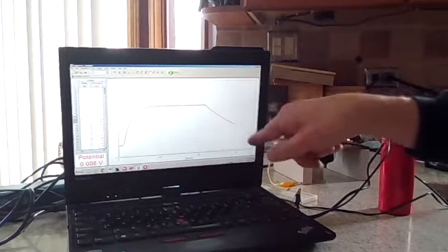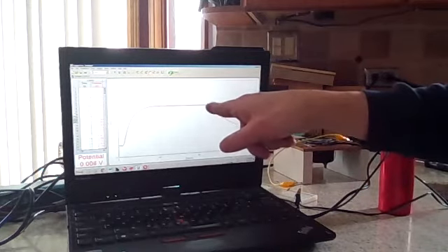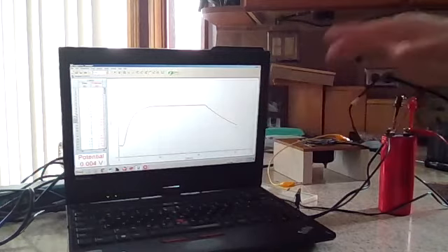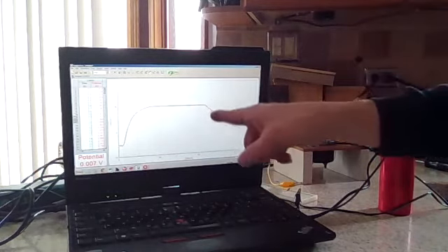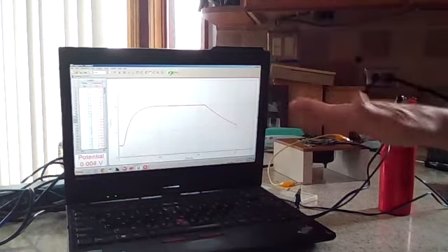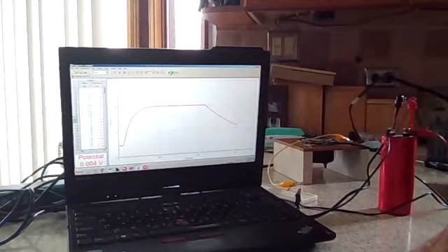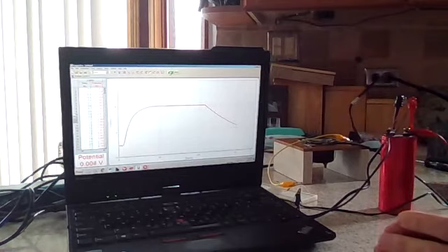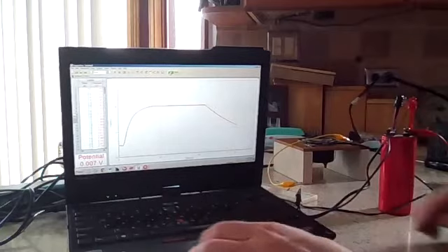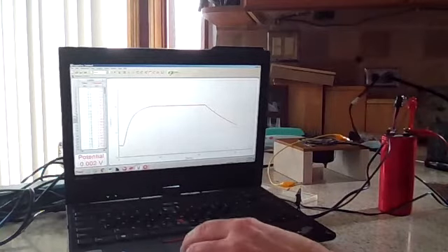And then if I turn off the power, it starts to discharge. And so if your capacitor discharges, it loses voltage, and that decays exponentially as well. Okay, so I want you to actually be able to see this, the real thing, instead of just talk about it in class. Okay, so what I'll do is, let me start collecting data here.